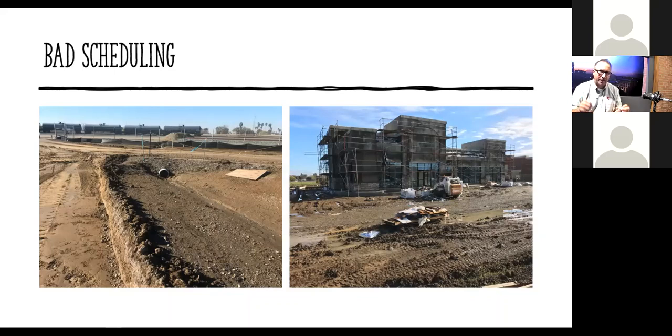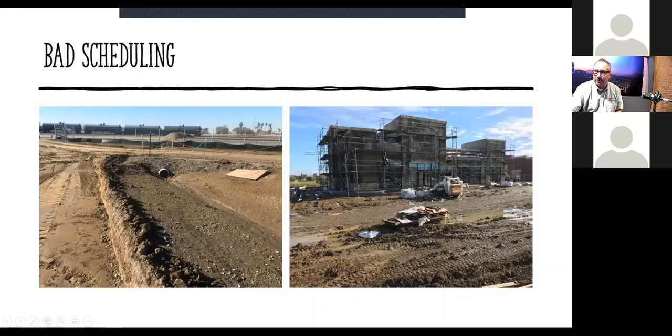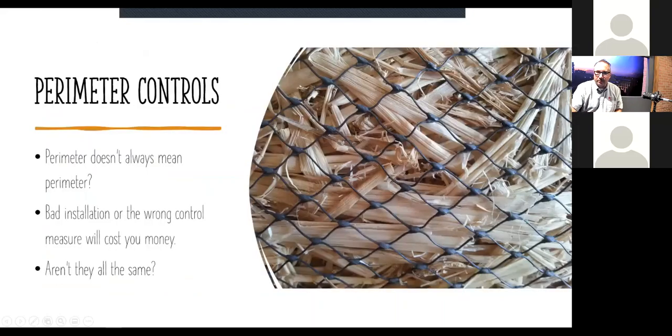Yes, we understand that having 2 lifts of asphalt is more expensive than 1 lift. But you have to weigh the cost of doing all this over excavation, dealing with extra track out issues, and compare that to requiring a second mob to do the second lift of asphalt. A lot of people are finding that is much more cost effective. Feel free to text in comments or questions. I'd love to see your comments on it.